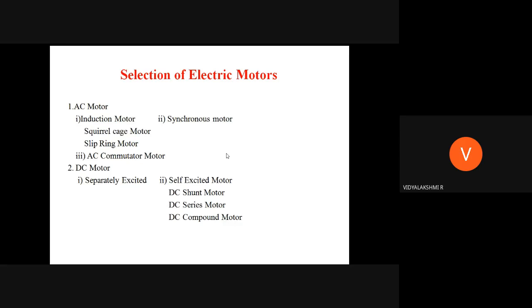The special requirements are fast, accurate and continuous speed changes, which means continuous speed control over a wide speed range. There I can use DC drives instead of AC drives. DC drives are used in paper mills, rolling mills, mechanical processing and positioning of heavy articles. And in such applications, we can use the separately excited motor.